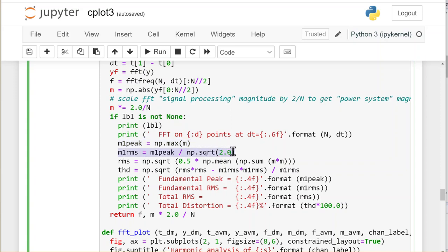And I should say, in the FFT in SciPy, you can do what's called a mixed radix FFT. So you can do it on exactly 1,000 points or 2,000 points. So you don't have to necessarily apply windowing to the time domain data before you do the FFT on it. We can do it on exactly 1,000 points and not a power of 2. We're not limited to 1024 or 2048 points.